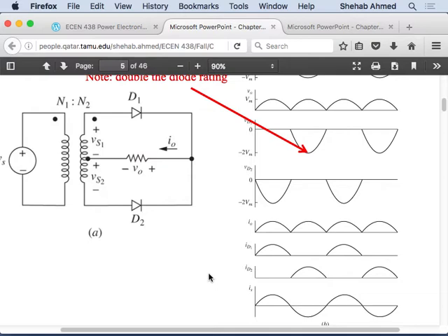And then come along these very low loss type devices that people don't care to use this stuff anymore, because the losses in these devices are already very low. So I don't care to really do zero voltage switching or zero current switching because, fine, it complicates my circuit, increases my cost. I don't care about efficiency anymore because I'm already getting 99.5% efficiency, for example. Right?